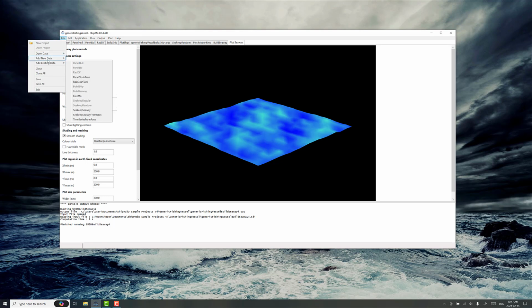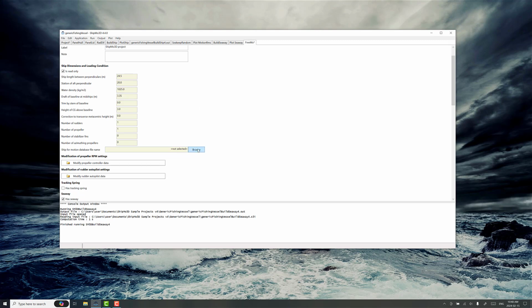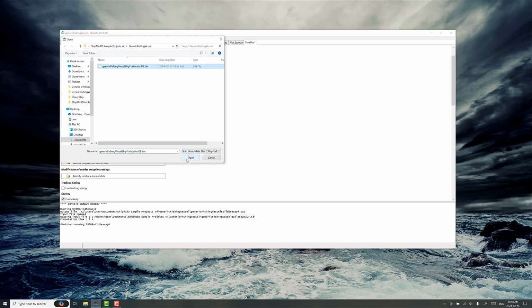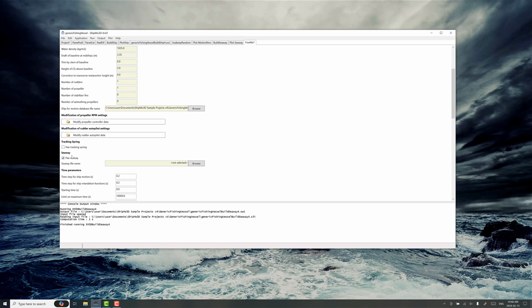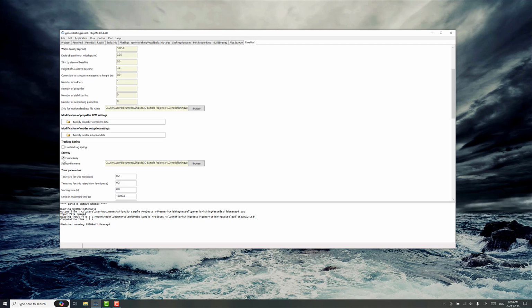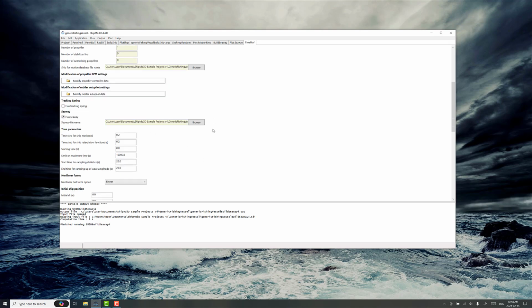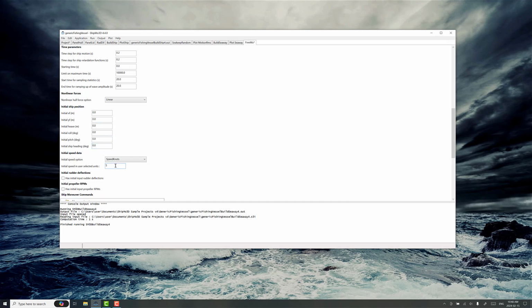The next step is to set up a FreeMo analysis. Again, this is the time domain analysis. What we're going to do is pick our ship motion model file, which is the output from build ship. We select that, and we want to make sure we have seaway selected, and there's our seaway file. Of course, you don't have to have a seaway. If you don't have this on, it's just in calm conditions, which is obviously ideal for doing turning circles or zigzag tests and so on. We are going to have the ship go straight at a 0 degree heading. It might be nice to have some initial speed.